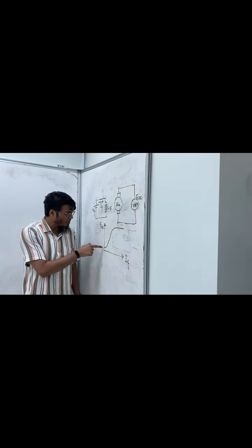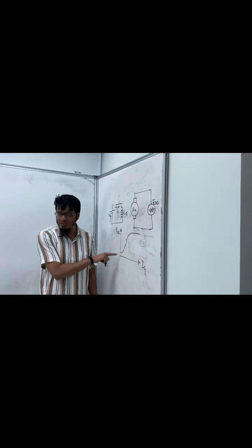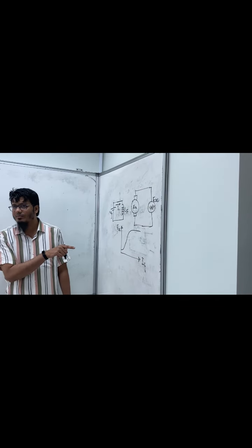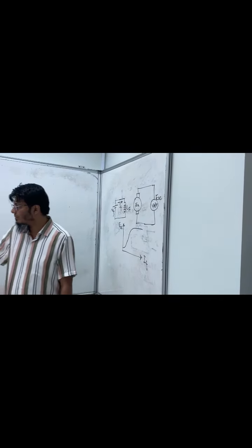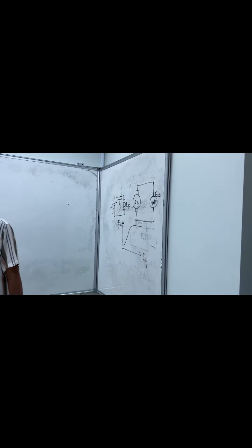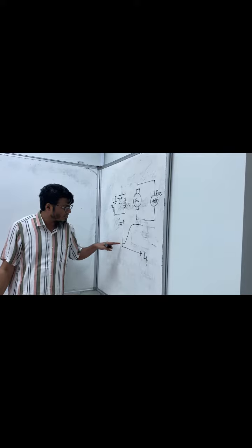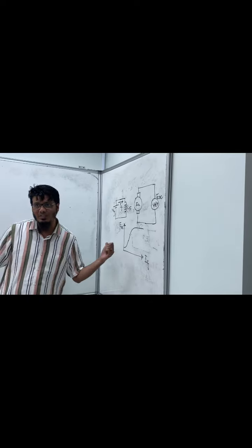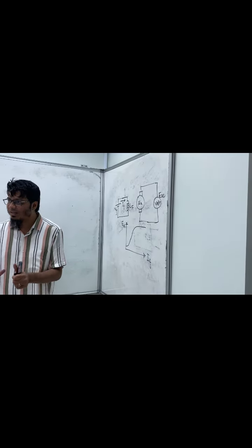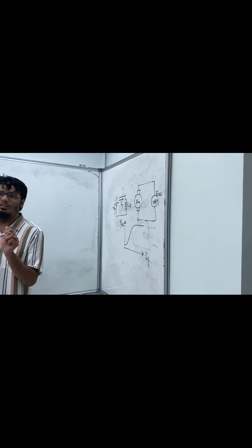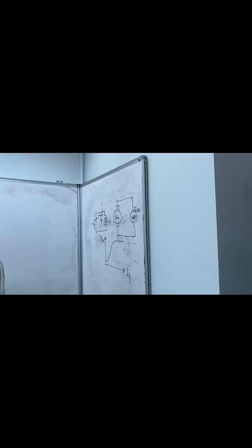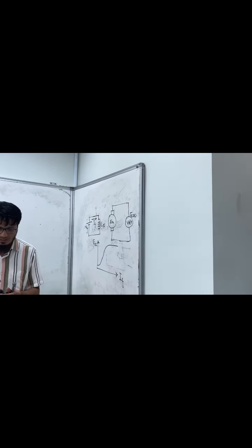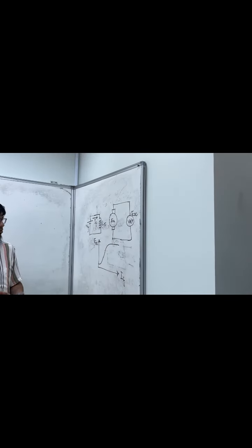Now, we usually don't start from 0 volt. Have you noticed? I have started just above 0. Can you remember why? But doctor, this is only for the self-excited. Not self, this is separately excited. No, this residual magnetism is present everywhere. But in self-excited, we take the advantage of this. Because the residual magnetism is everywhere, but in separately excited, we don't need it because we have a separate excitation. In self-excited, we take advantage of this stored residual magnetism. We discussed this in lecture. If you have a question, we can discuss again in the lecture class. I don't want to go over there.